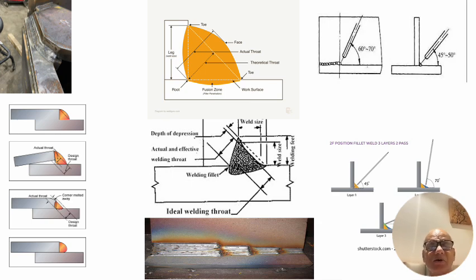As it is, the corner joints are already highly stressed, and the last weld which we will be doing here, which you will see in the subsequent slide, is also a highly stressed one, because already there is so much weld which has happened before we deposit the last layer here, and we will start building up from the bottom. So the last layer is always going to be from top to bottom.